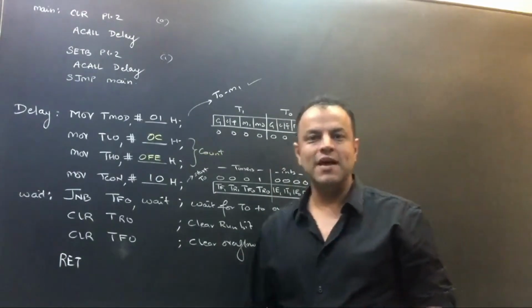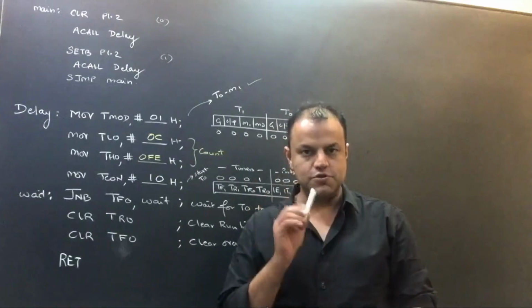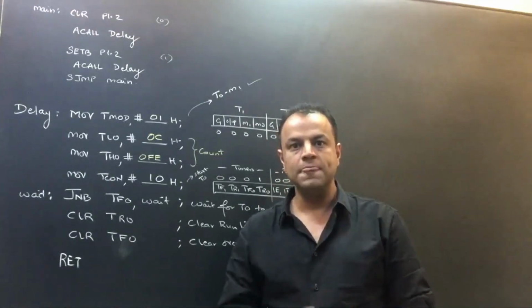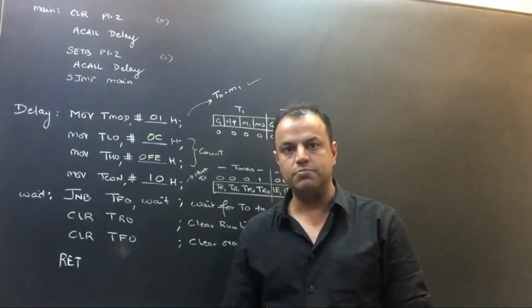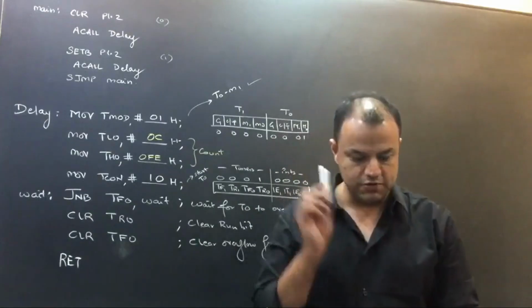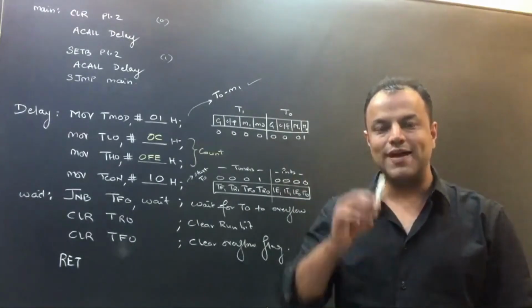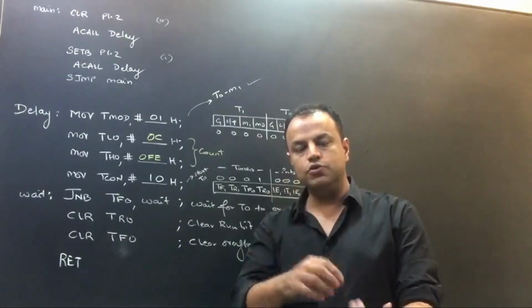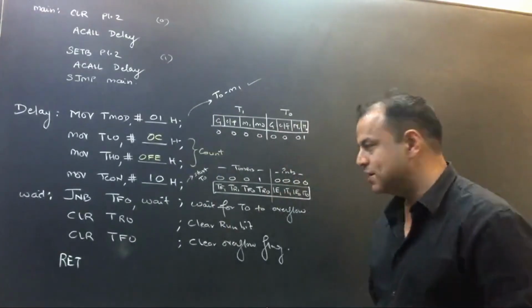Did you understand this? I am telling you, when you finish your job, keep this chalk here. I will keep looking at this in my hand. Whenever the chalk comes here, I know you finished your job. If you keep the chalk here before you started the job or while you were doing the job, how will I come to know when you will finish the job? Because you are supposed to keep this chalk here. That is the timer overflow flag. When the timer finishes, it will make the overflow flag 1. So you will keep the overflow flag 0. Tell me, did you understand this?